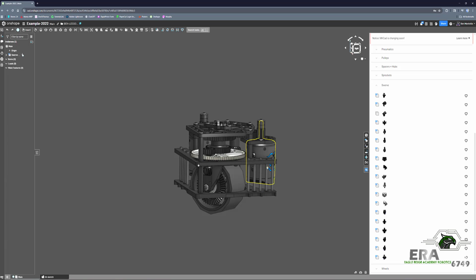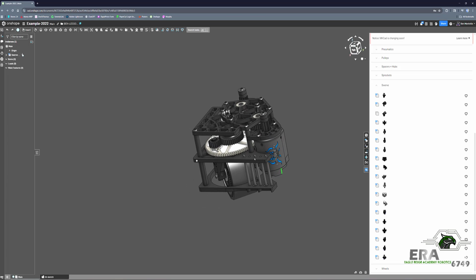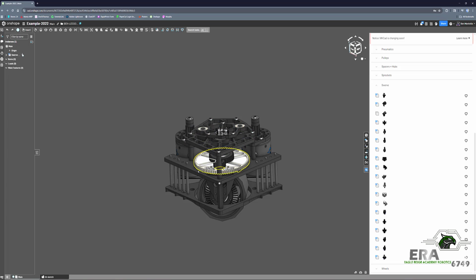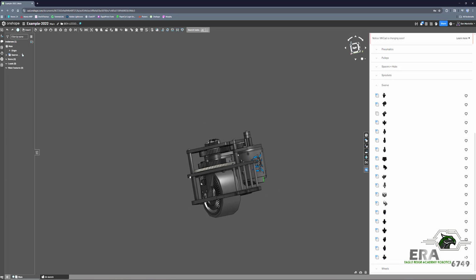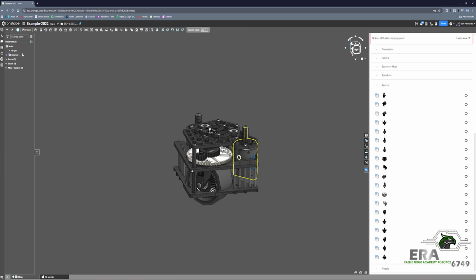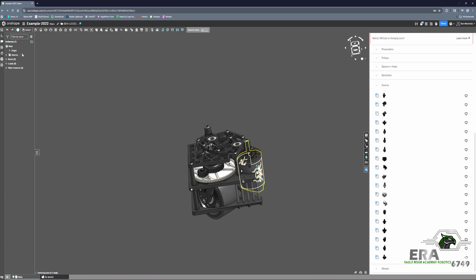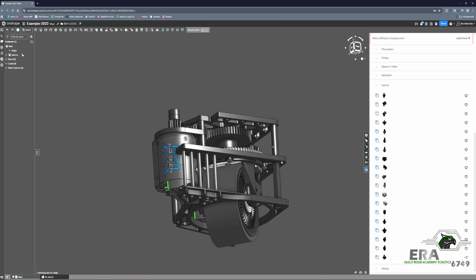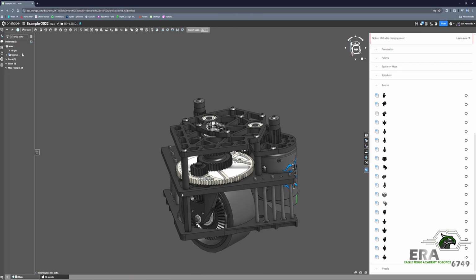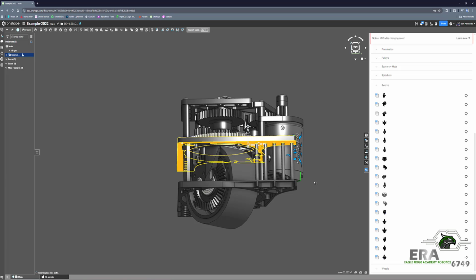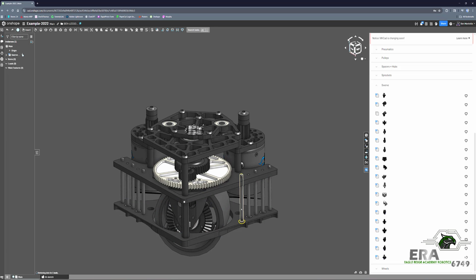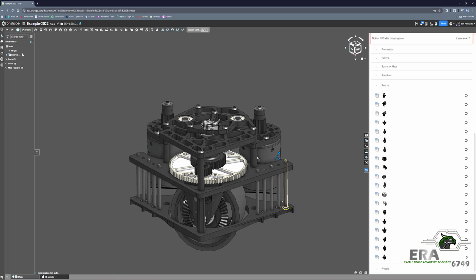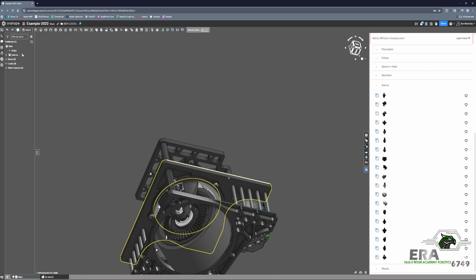The handy thing about having this all on hand here is that I don't have to go and find any measurements in the real world. I can use all these because I know these assemblies are based off the same setup that we have. The inner gear ratio might be a little different, just because I don't know exactly what we have. I'm pretty sure we have 12 tooth, but I could be wrong. But aside from that, we're still able to get all the measurements we need. Just by the looks of this, you can tell that our 2x1 frame is going to go in here where these bolts are. These bolts will go all the way through the 2x1, working to clamp it in.